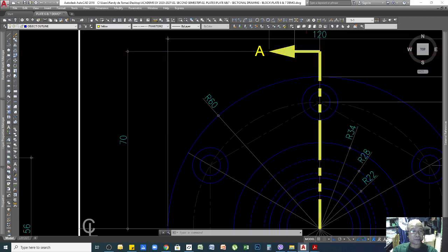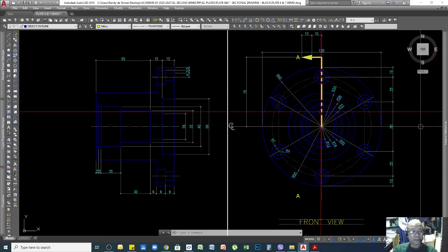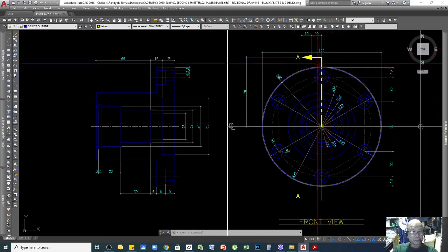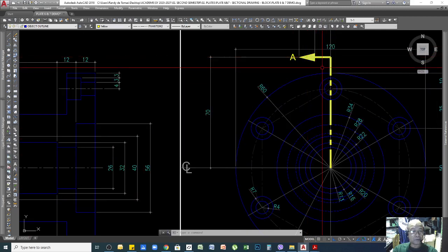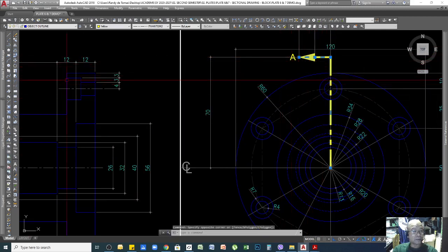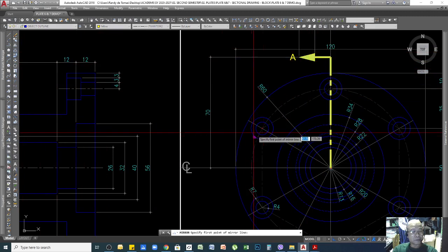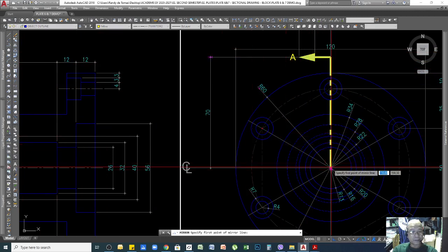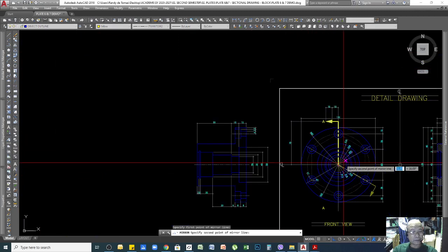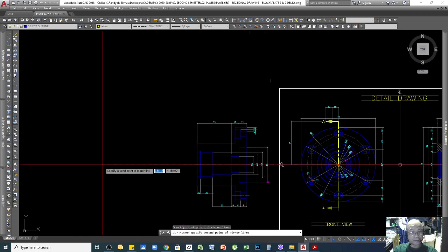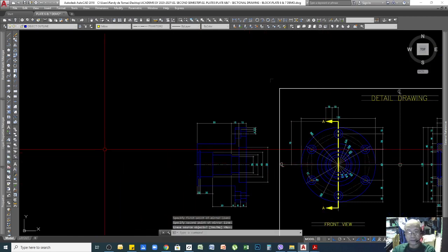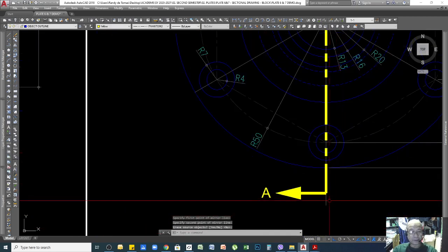So you need another polyline below. All you need to do is click this one and then use the mirror command or the icon. Then click this one, move your cursor left or right, and then click and enter. So it is there already.